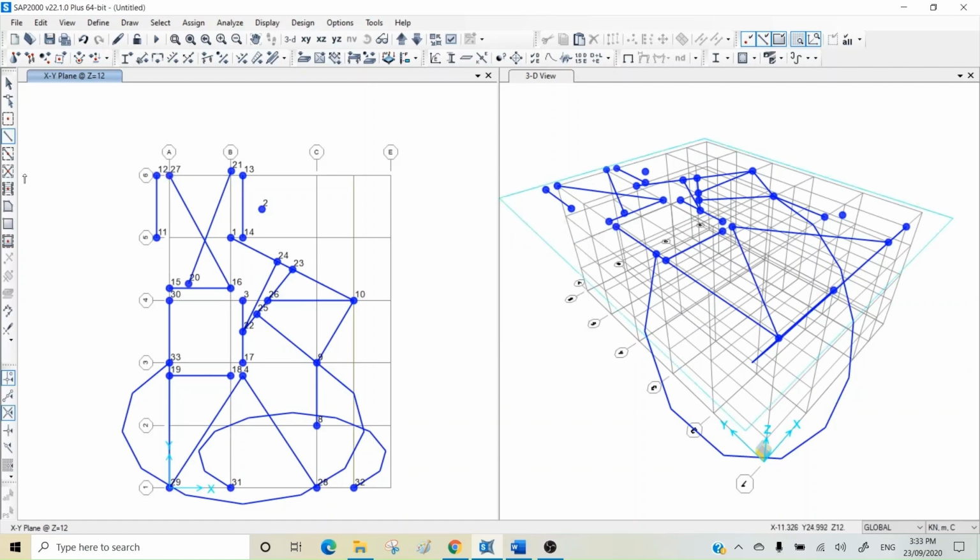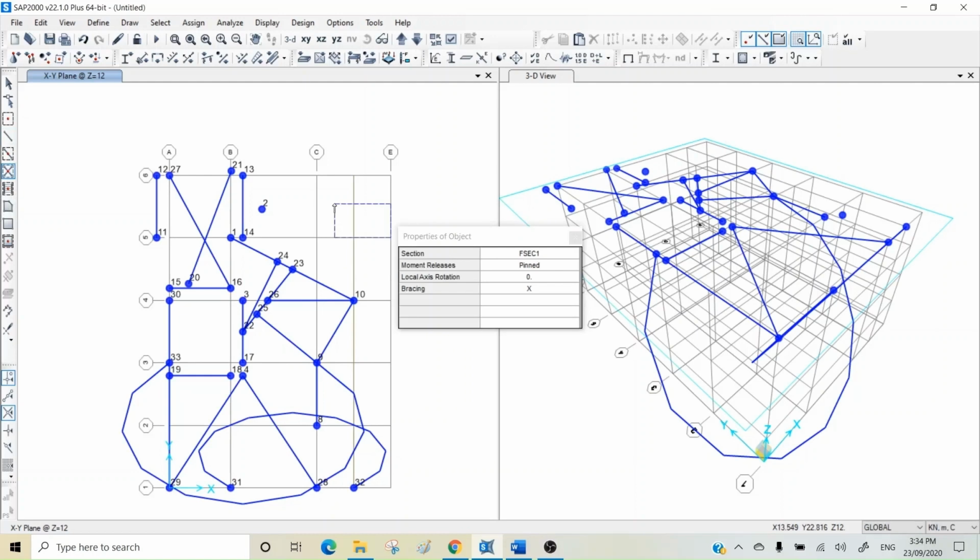I'm going very quickly through the two other options remaining. One is for brace and one is for secondary element, to wrap up drawing for elements, and then we will leave shell elements or area elements to the next video. So for bracing, you can come here and just click on any span between any grids, and that will draw for you here. You cannot do it in 3D view. You need to find an elevation and then do that.